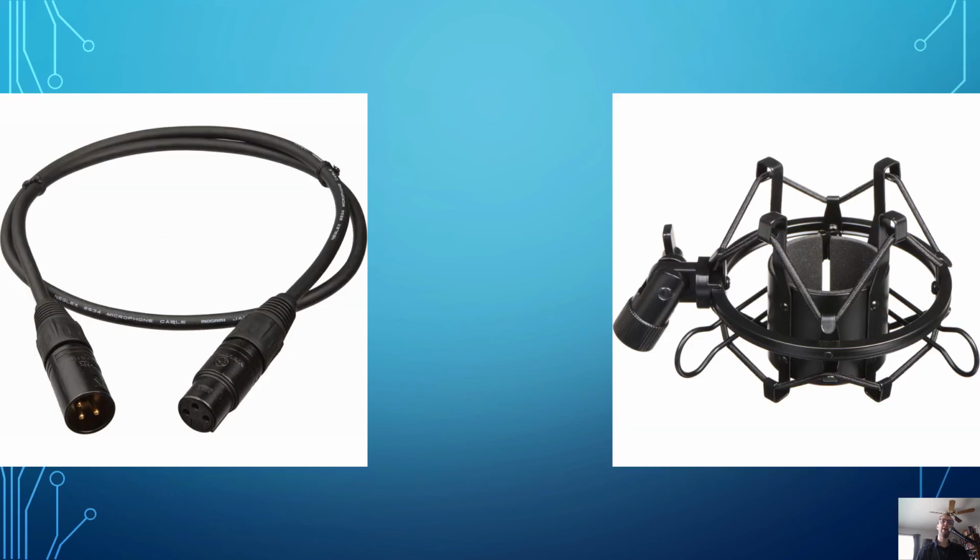Here is a picture on the left of the XLR cable. Note that it has 3 prongs that it uses to connect. It carries ground on one, and then it carries a balanced signal. So there are actually 2 copies of the signal from the microphone going. So if something happens, you can swap the pins and still get a signal. On the right is a shock mount. It just suspends the mic in an elastic band that reduces those vibrations and keeps it from recording any handling noise. Very, very handy device.